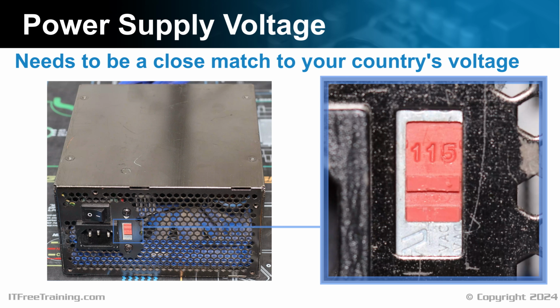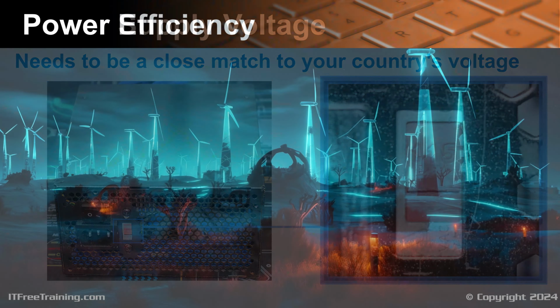If you're in a country that uses 120 volt power supplies, you'll find that data centers will often use 240 volts or even higher voltages, because higher voltages are more efficient. Whatever voltage is used, make sure it matches. The power supply should be clearly marked which voltages it can be used with, and using the wrong voltage will cause damage. There are some other things that you may want to consider when purchasing a power supply.